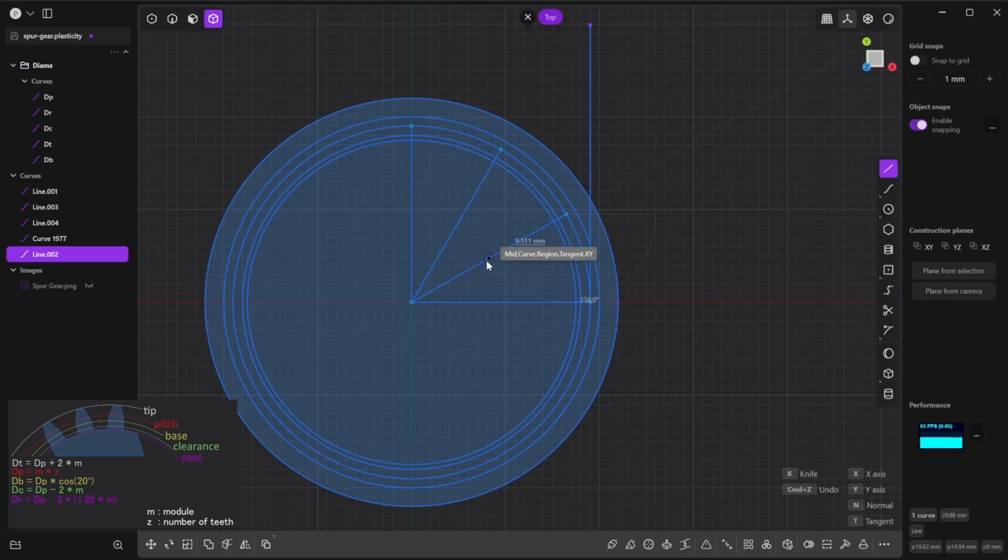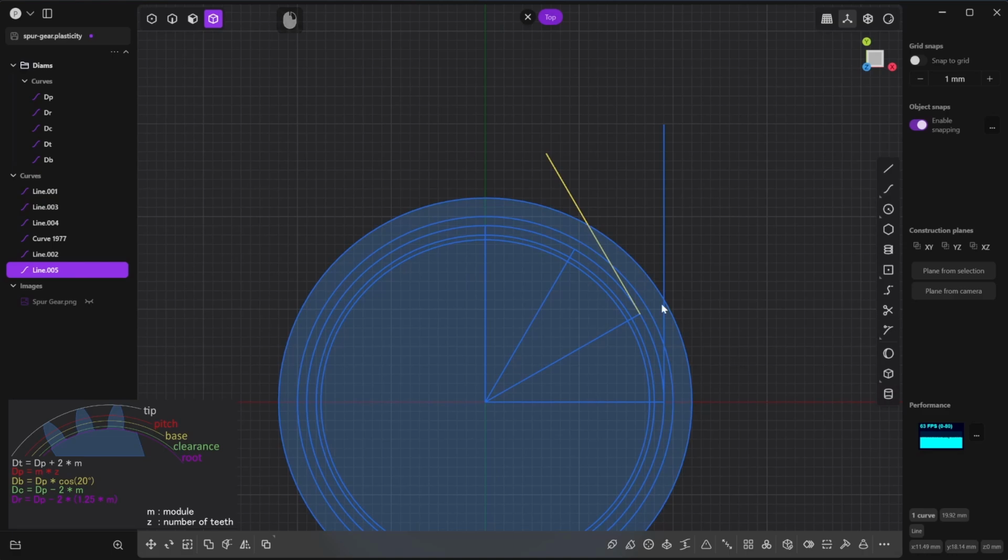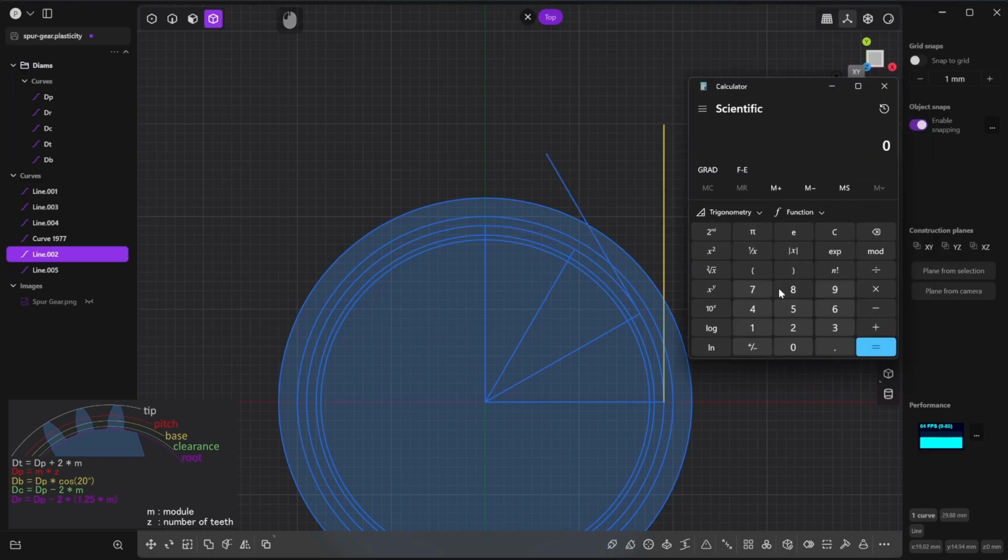If we have here 150 and here 30, this means that 90 degrees is going to be 120 here. And we set the length we just calculated. So the last construction line we need to build is going to be perpendicular to this radius and is going to be equal to the length of this third. We remember that the length of the quarter of the circumference is 29.871. So if we divide it by 3, this is going to be 9.5936. This level of precision is good enough for me.